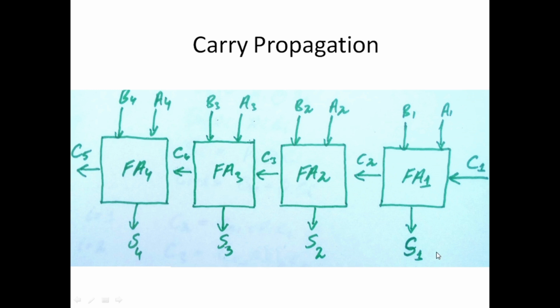Okay, so there is a problem with this adder when the two numbers are provided simultaneously to the 4 full adders, but these 4 full adders would not function at the same time because they are dependent on each other. For example, this full adder 2 is dependent on the 2 bits provided here and the input carry, which is actually the output carry from the full adder on the right.